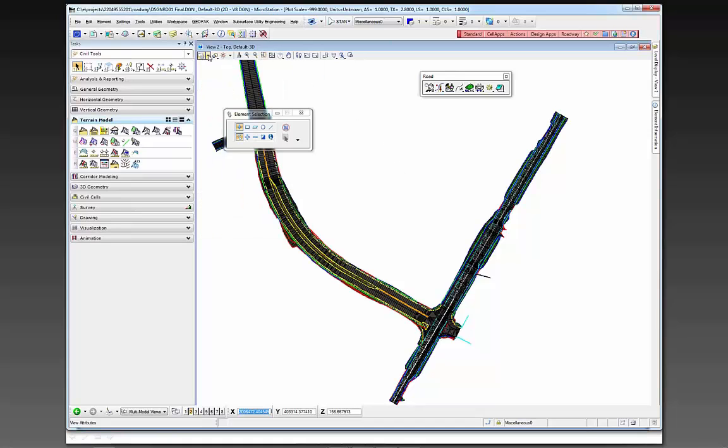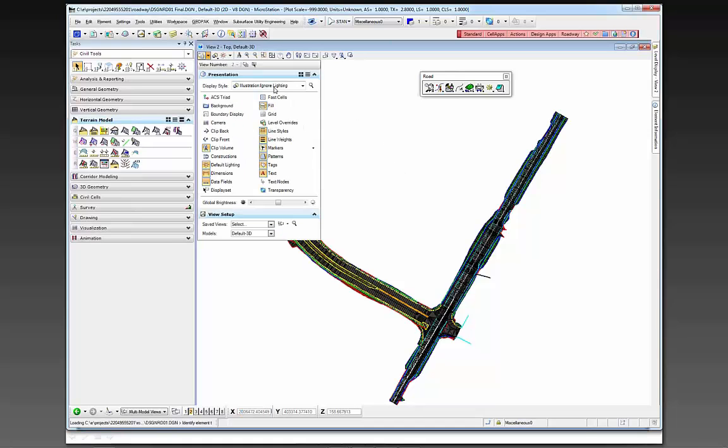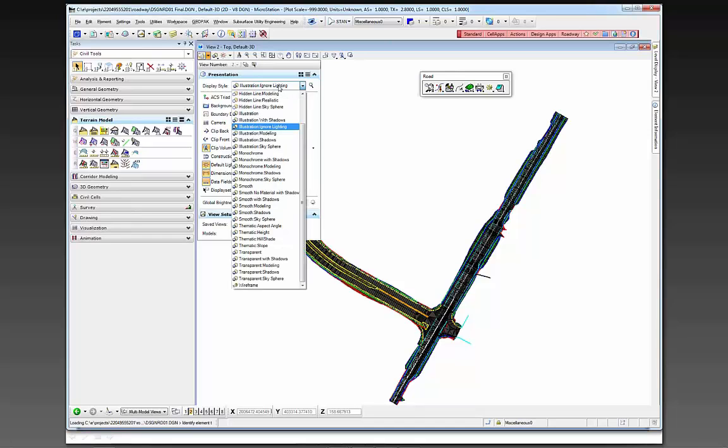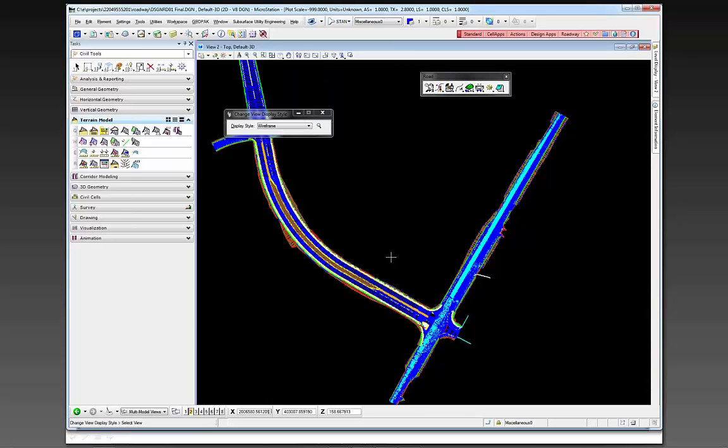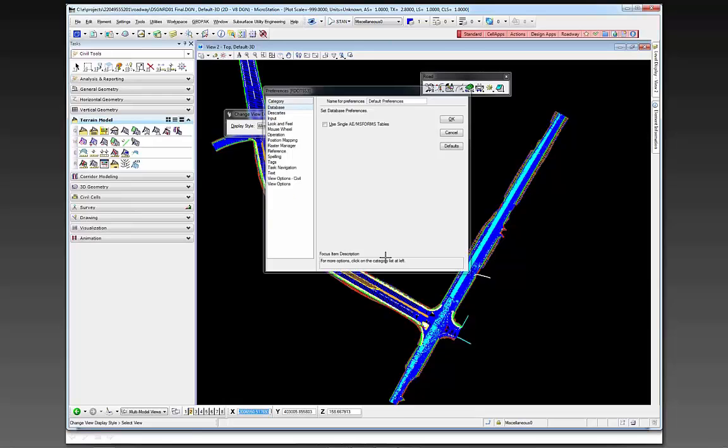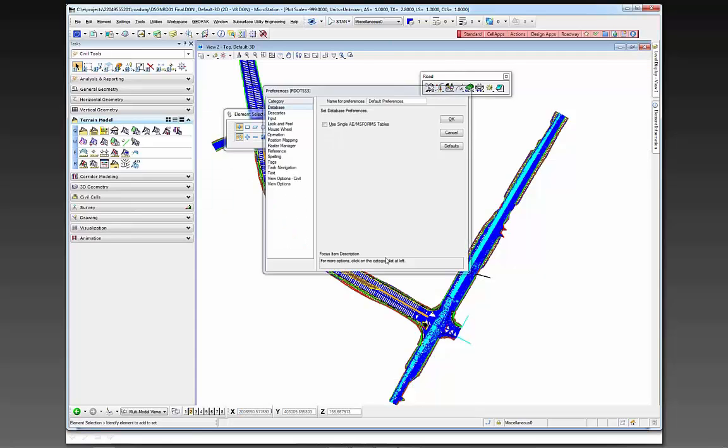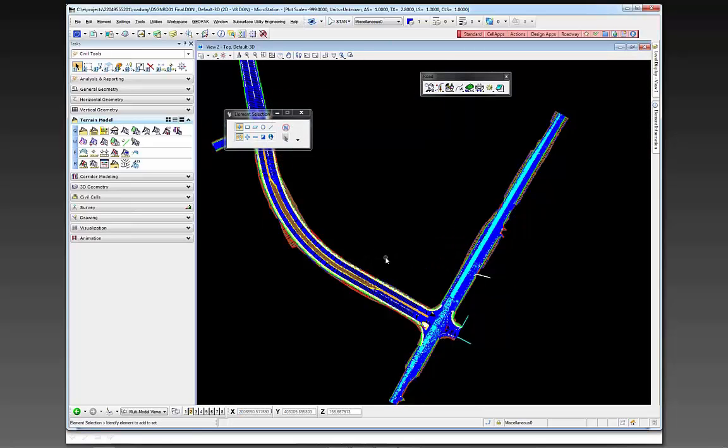And I would also work from a wireframe. So you can go to the view, and right now, usually with the F2 key, it sets it to an illustration, ignore lighting type mode. That's how you can see them shaded. So if you just go back to a wireframe mode, and then sometimes the background is white. If you want to set that back to black, you're welcome to, just with the F5 key.